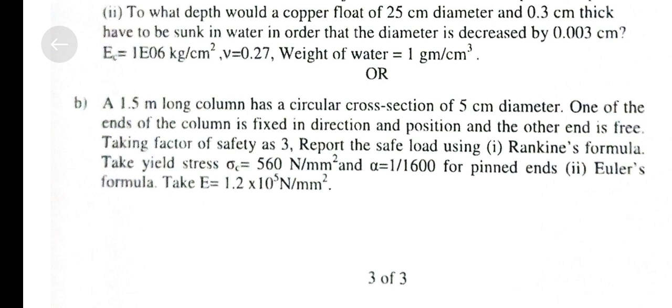σc equals 560 N/mm², and alpha equals 1/1600 for pinned ends. Euler's formula. Take E equals 1.2 × 10^5 N/mm².